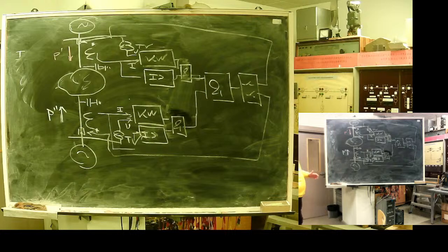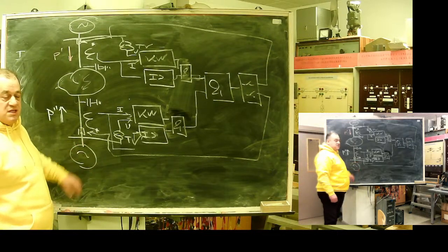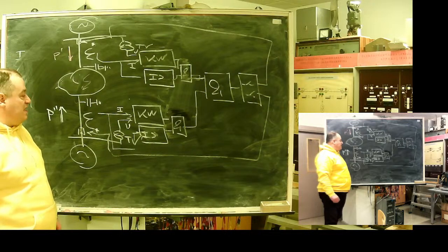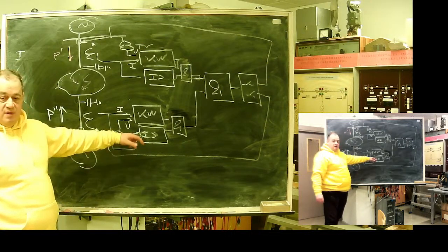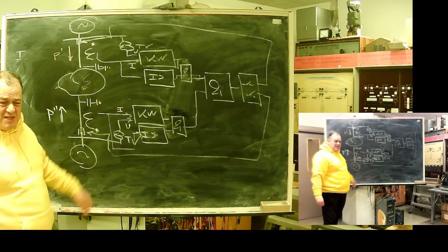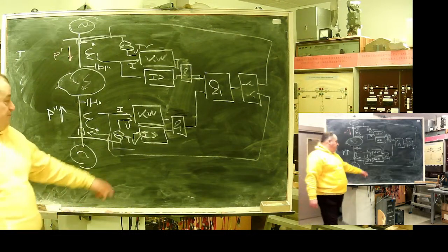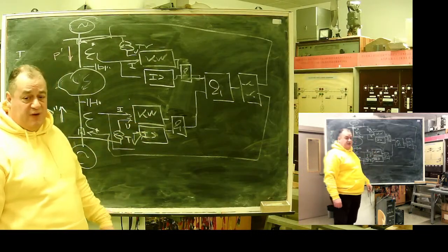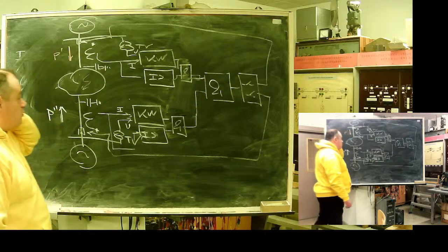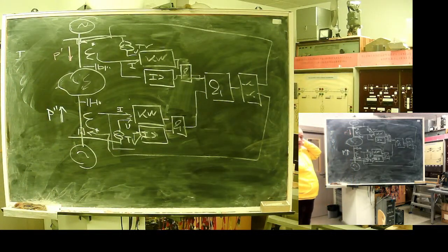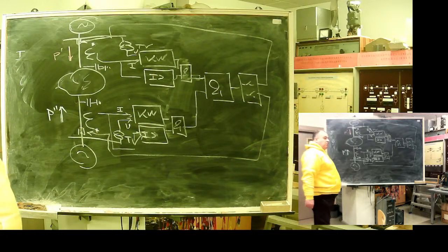It appears safe, but it's not reliable when one of the sources is disconnected, because it's mandatory to have a current threshold. Without a current threshold, it will still be unreliable, because this element can operate falsely from noise. So these schematics appear to be good. It's repeated multiple times, but it's not as reliable as it appears.